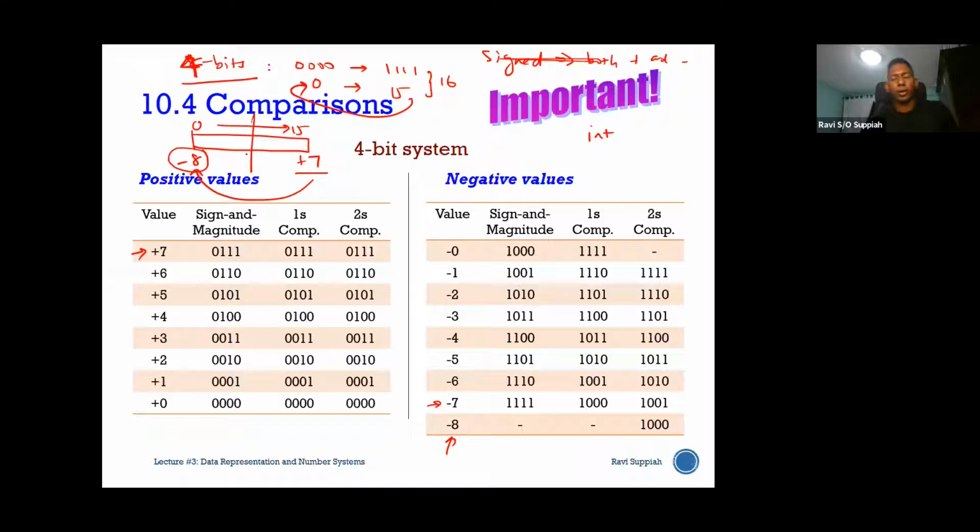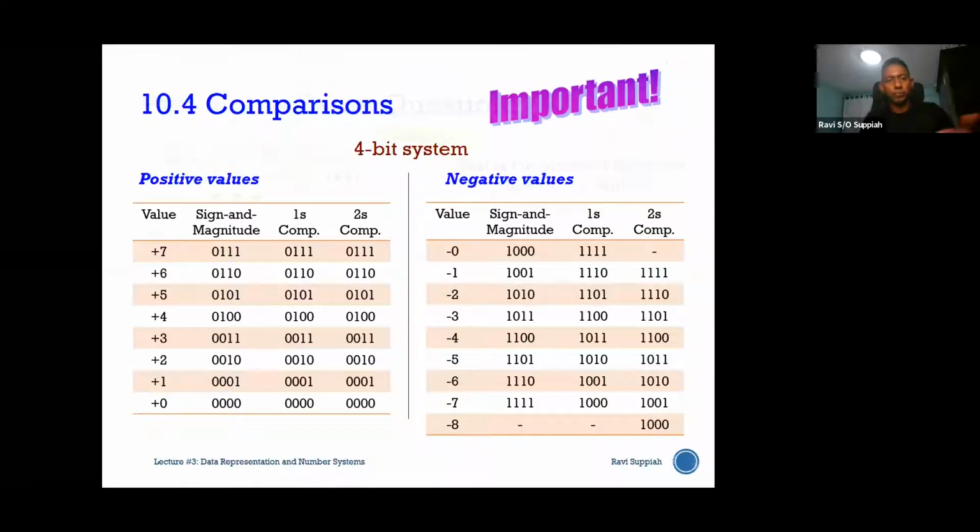Okay, so when I'm at the topmost, that means the highest positive number, and I add 1 to that, I will actually roll over to the smallest negative number and then start counting upwards from there. That means if I count plus 5, plus 6, plus 7, then it will become -8, -7, -6, -5, and so on. So that is how the system behaves when you overflow from the maximum value.